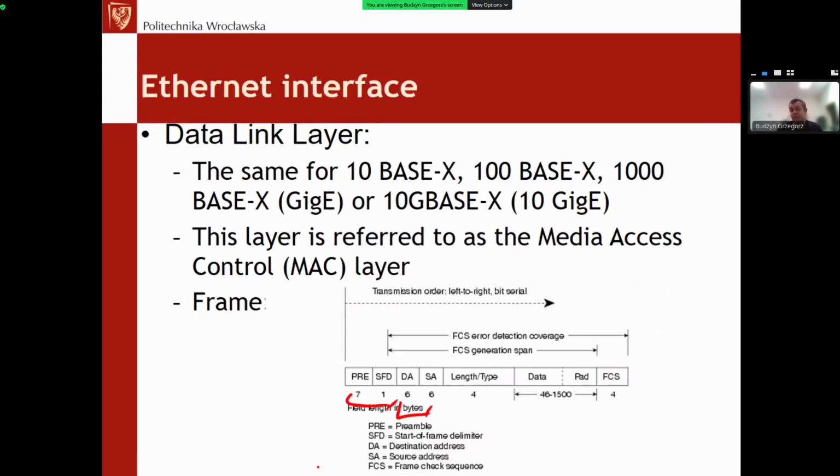Second of all, we've got source and destination address directly at this level, which means that the receiver will have information about where this frame came from. This is different from CAN or I2C, where just the destination address is in the frame.